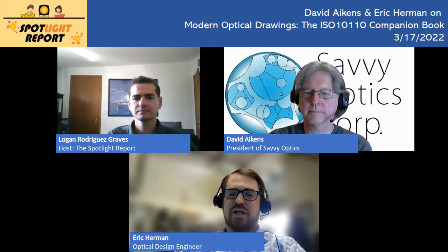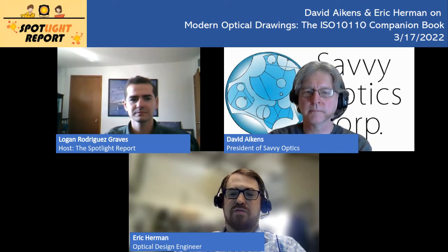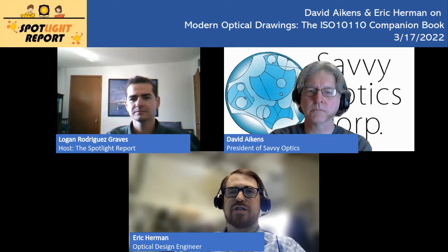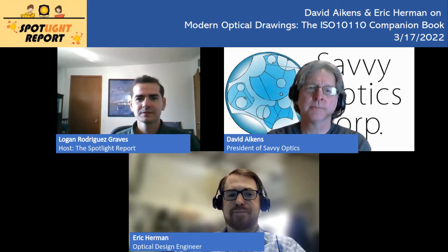The homogeneity is just what is the refractive index through the part? How much is it going to change? And your stria is, if it is going to change the refractive index, how much is it going to change at some given period, in frequency? Mm-hmm. Spatial period. Yeah.